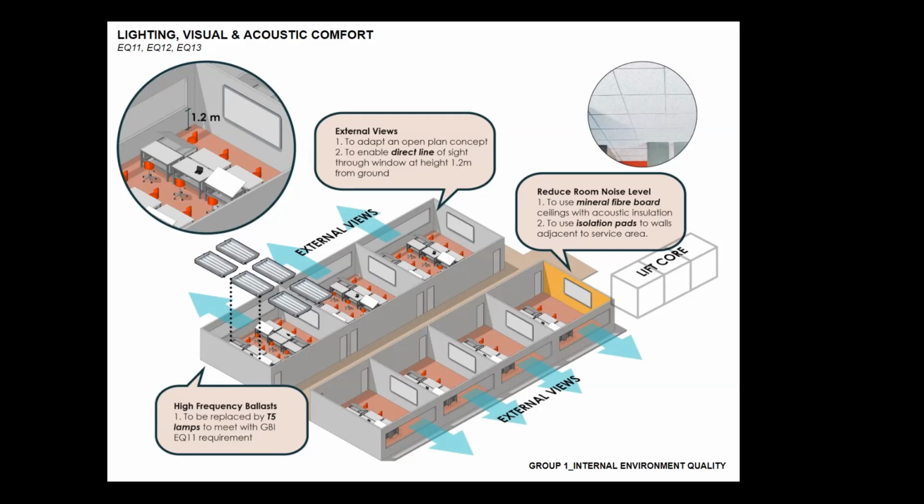So on both main sides, which are north and south, no obstructions whatsoever, fantastic views of Kuala Lumpur and PJ. So we should get a good point there. And then noise level, of course, we have acoustic tiles on the ceiling, and the partitions are acoustic as well. But you need to check the BQ for the partition and for the tiles, okay? Get the specification. If we're not meeting that target, then perhaps you can suggest something there, all right?